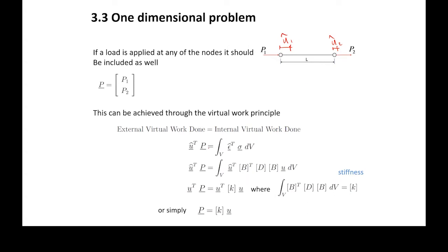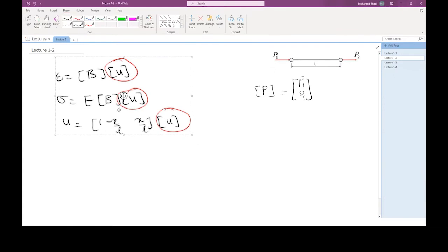All right. Now, this is basically the external force: the virtual displacement you had multiplied with the forces we have already on the problem. And then you have the virtual strain multiplied with the actual stress, integrated over the volume. All right. So I'm basically just going to write this expression and expand it. This is what I'm going to do here.